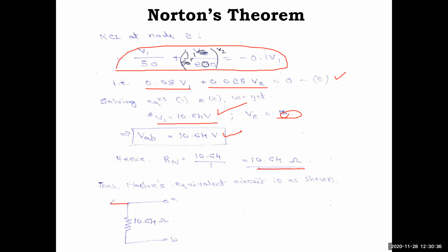Okay, even you can show this, or you can show the current source also. This is the current source in parallel with the resistance in Norton's, but the current source is 0 amps. Like that also you can show it with a symbol, 0 amps, which is nothing but an open circuit, equivalent to a single resistance. Hope it is clear.